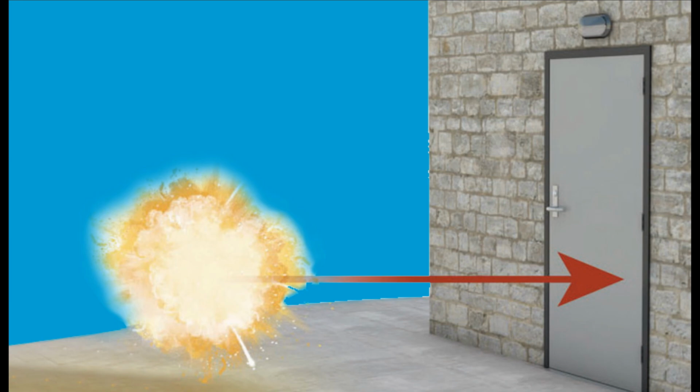As far as what kind of blast you have, do a takeoff on the doors and frames like you normally would. The other big piece of the conversation is, is it seated or unseated? Different from interior or exterior. Seated means the energy from the blast hits the door on the pull side, and it seats the door into the frame. And unseated, of course, would be the door on the other side, trying to blow the door open. As you can imagine, hardware becomes a much bigger factor in the unseated condition.